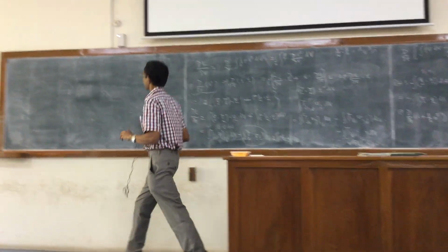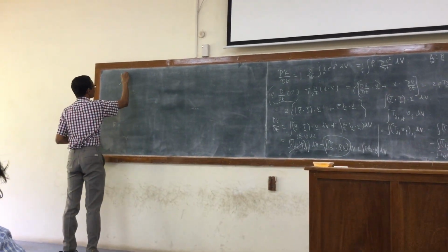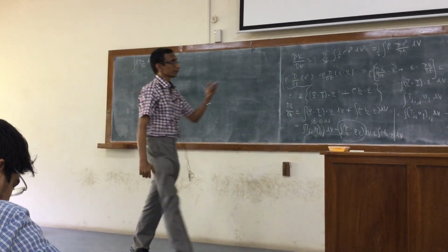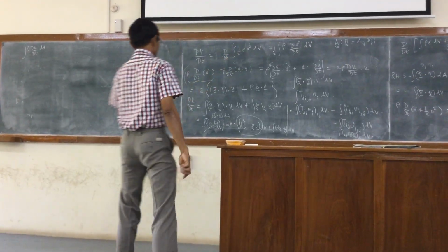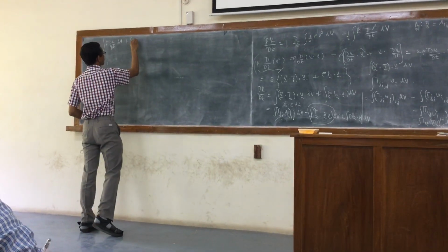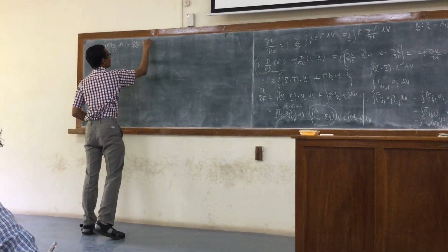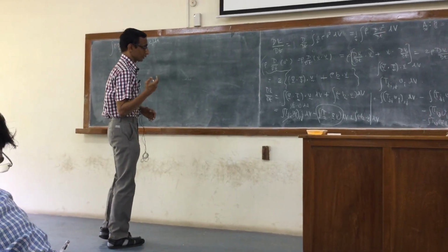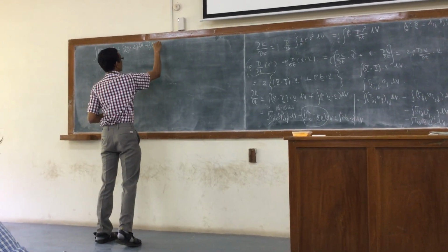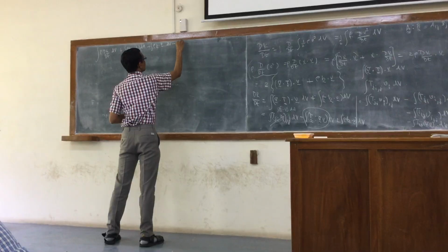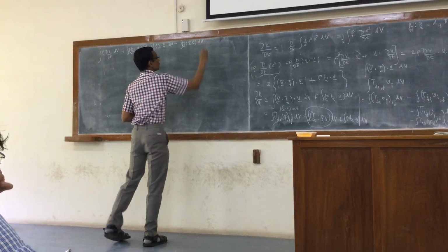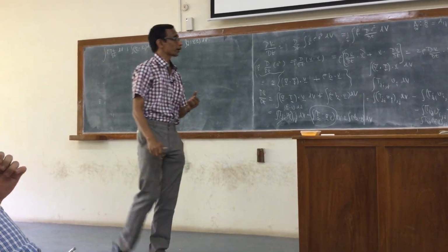So what will I get? So I get integral dV plus this, which will have plus integral, I write it as T dot v, doesn't matter how you write it. Now I choose to write it the same way on the other side, T dotted with v dA plus integral b dotted with v dV minus integral T double dot with the velocity gradient. So I have all that.